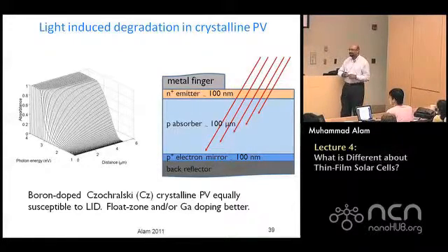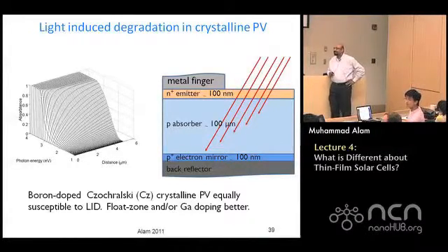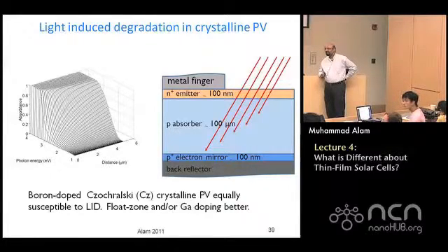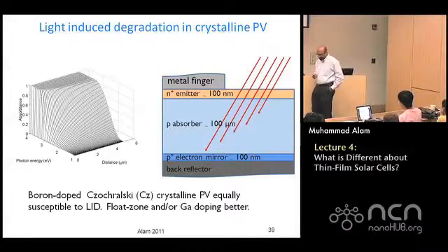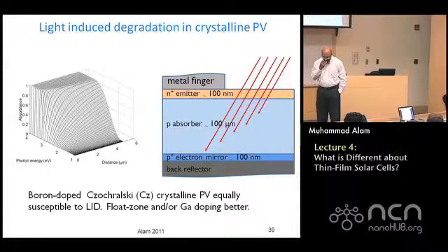Yes. So you showed us a nice derivation of the IV characteristic in terms of the transmission to the left and the right. So when you measure the dark IV characteristics and get out of the shunt regime, at the higher voltages where you just have the junction current, what's the diode factor?